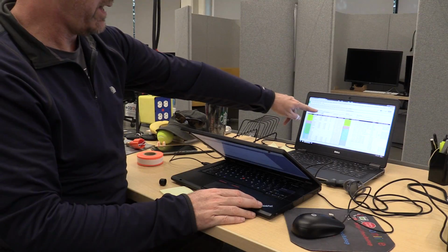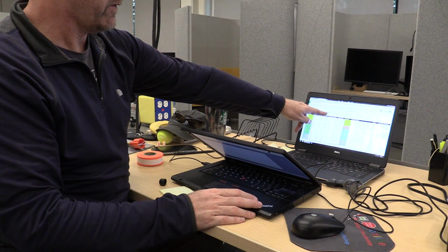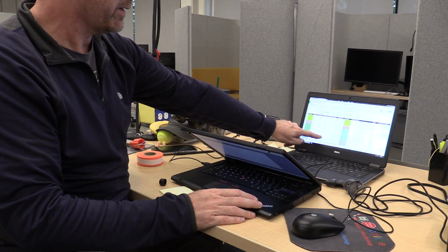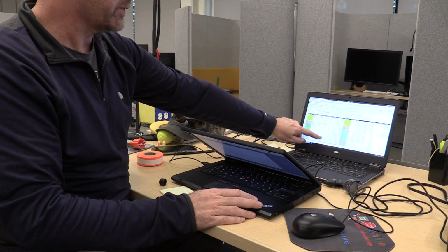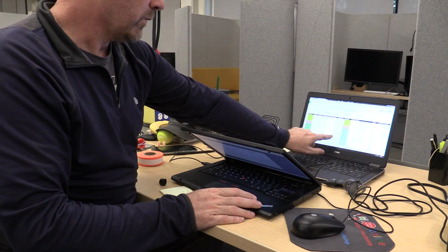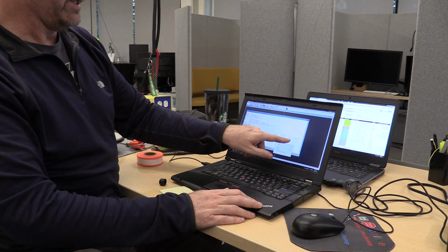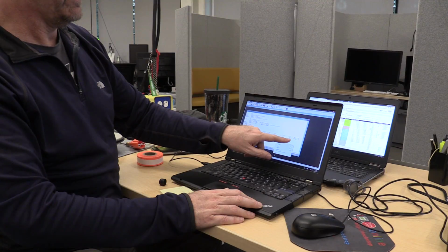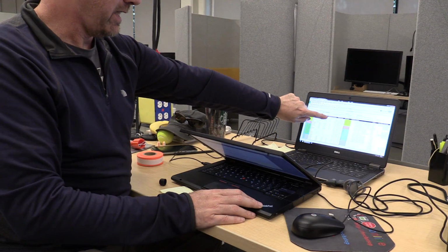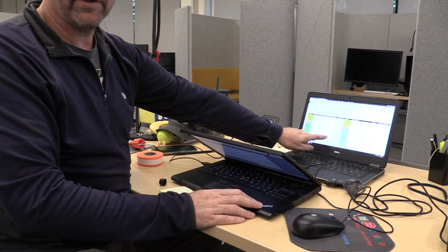That's why we have this tool here, degrees, minutes, seconds, decimal, so we can convert it to degrees decimal, and that's what we actually populate the table with. So we have to grab each one of those lats and longs and do that. Okay, and then when we pull the elevation, which is 3 significant digits, we pull that in, and this will automatically round to two significant digits. We just pull that directly in.